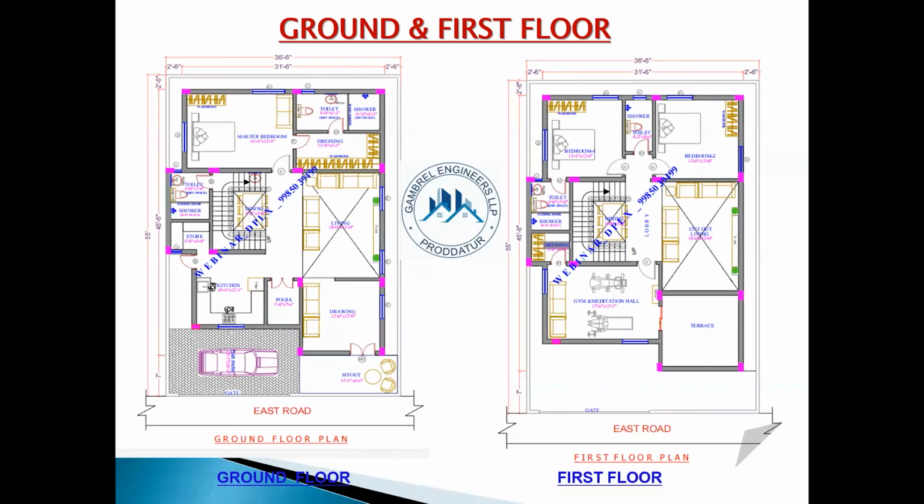And a second question: Dhirendra Prasad is asking, why can't we eliminate the columns at the storeroom and the toilet corner? Is it possible? No, we have to have a column here, as I have explained, here and then here. If you avoid it, this beam is going to act like a cantilever, and this is going to rest on it, right?